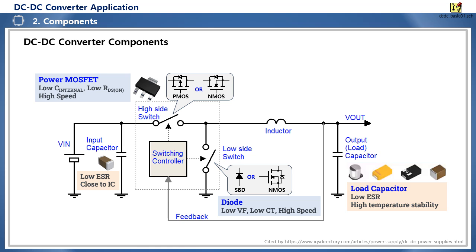On the other hand, MLCCs have low ESR characteristics, so they have small ripple voltage and low self-heating. In addition, their size is relatively small, which can reduce circuit space. Since MLCCs can affect performance by decreasing capacitance due to changes in ambient temperature or DC bias effects, an appropriate type of MLCC should be selected considering this.